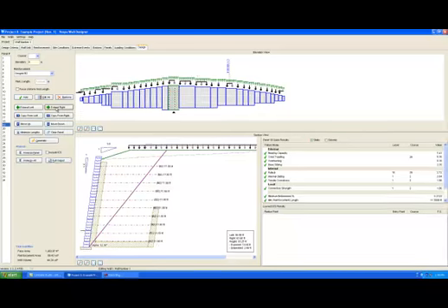Since we have started at the highest panel and the loading is also the worst case at this point, we can rest assured that if our Geogrid length and layout works for this panel, it will likely be conservative for lower panels. This will have to be checked, but it is a good place to start.